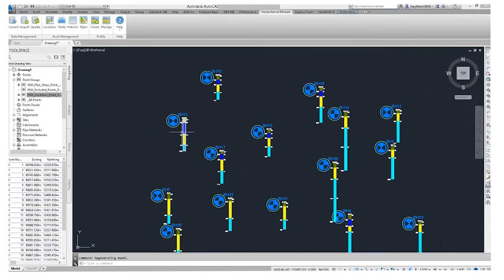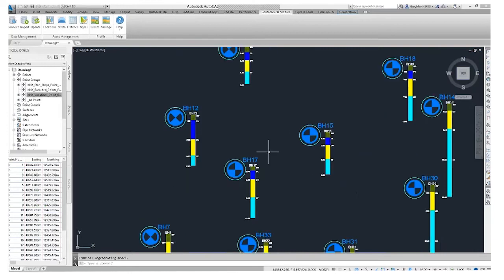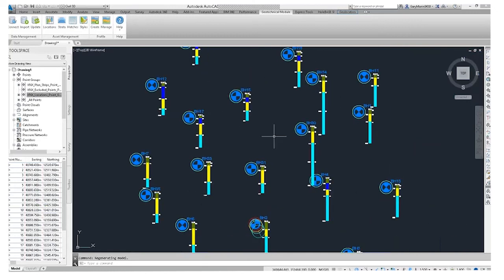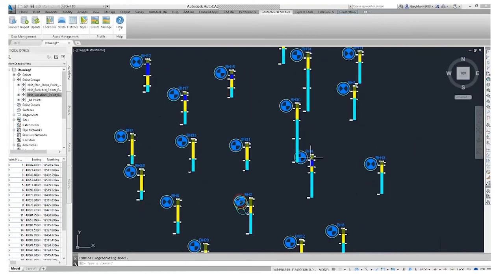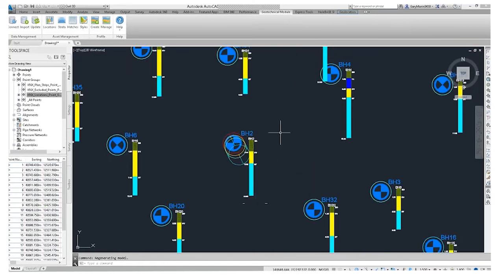So for instance here we can see the blue, we zoom in, we can see CL for clay, but we have clay at the top end of our site. We also actually have a clay lens a little bit further down in the site and some clay at the bottom. So these strips are really useful at showing what geology you have.